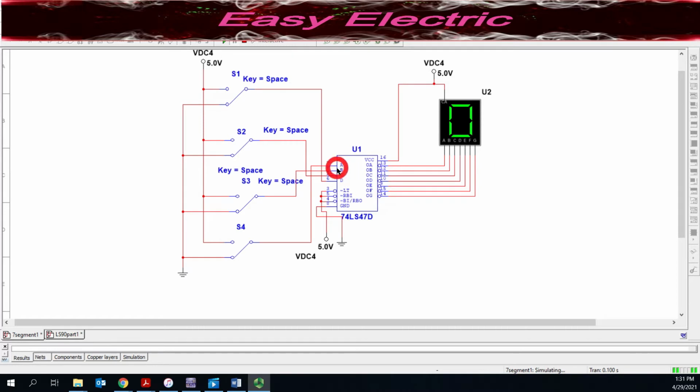As you could see here, the first 4 inputs, which is pin 7, 1, 2, and 6, you actually give your BCD codes. Here we connected them to the switch, and by turning this switch between 0 and 1, we are able to give 0 or 1 for each input that we have. So technically we could make a BCD code 0 to 9 through these 4 inputs.